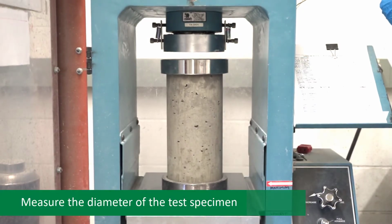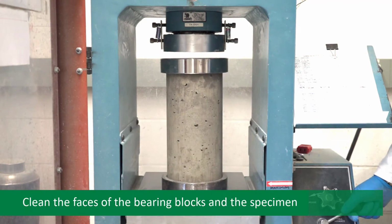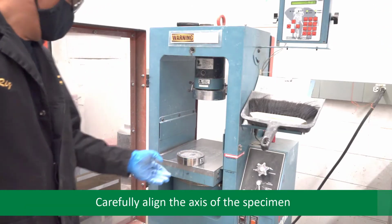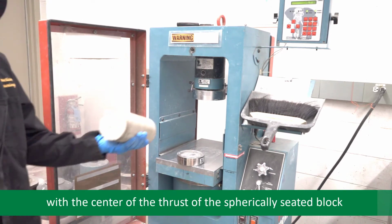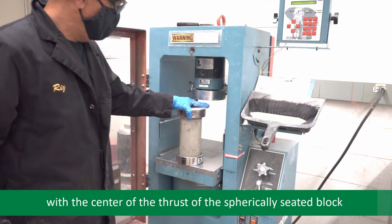Begin by measuring the diameter of the test specimen to the nearest quarter millimeter by averaging 2 diameters measured at right angles to each other at the middle height of the specimen. Adjust the bearing blocks into position. Clean the faces of the bearing blocks and the specimen. Carefully align the axis of the specimen with the center of the thrust of the spherically seated block.